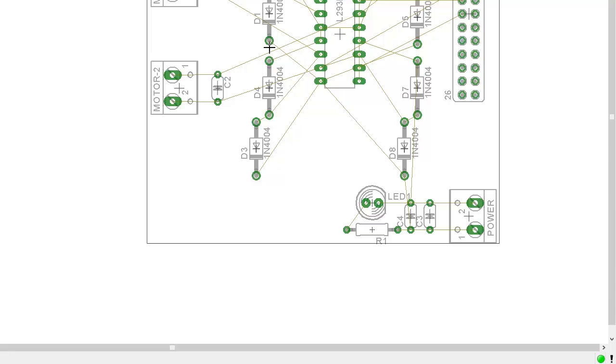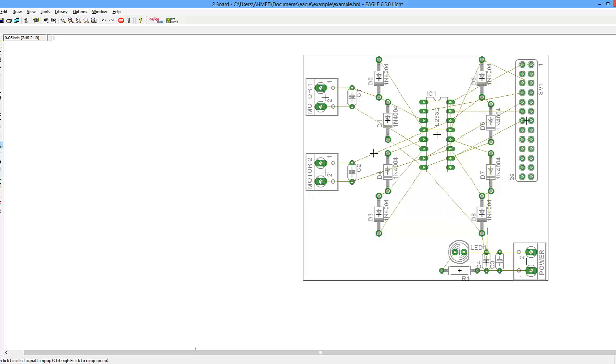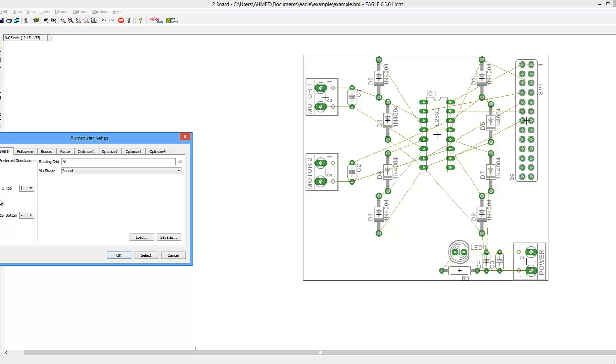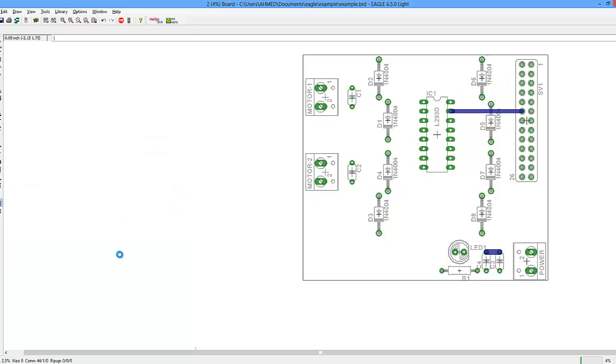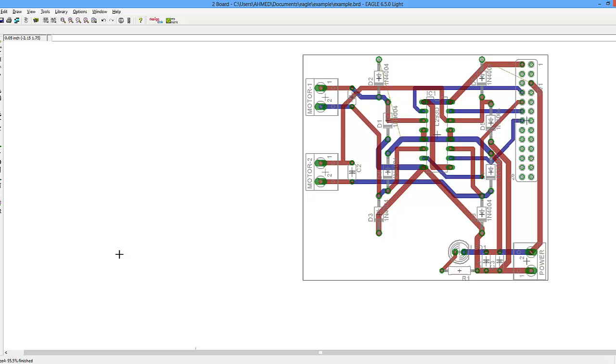First I will try the auto router without any modification. It's not a modification, just a small trick I'd like to use. So first I go here, which is auto route. Let's save, okay, save and then auto route, and right now the auto router will route from the top and the bottom layers. So let's start, say okay. Now it's testing. It's done quick. Okay, so it finished all the routing, but still it has two connections it couldn't do.